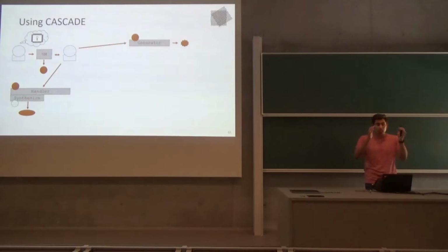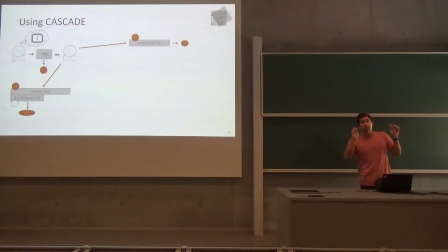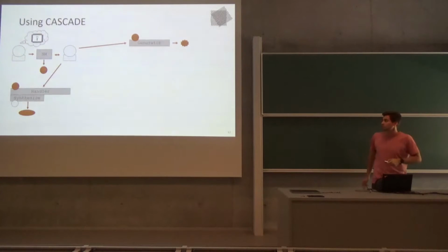Handlers basically encapsulate EDA tools, or some custom tools, but the idea is to abstract away the functionality. So whether you want to use a Synopsys Design Compiler or whatever the Cadence equivalent is, you can have this encapsulated way of handling it and hide it away from the designers. So here you're using these system parameters, and then once you're doing the synthesis, this little bluish circle is basically the only place where you have additional manual user input, because automating the synthesis, be it physical or logical synthesis, is a whole other problem.